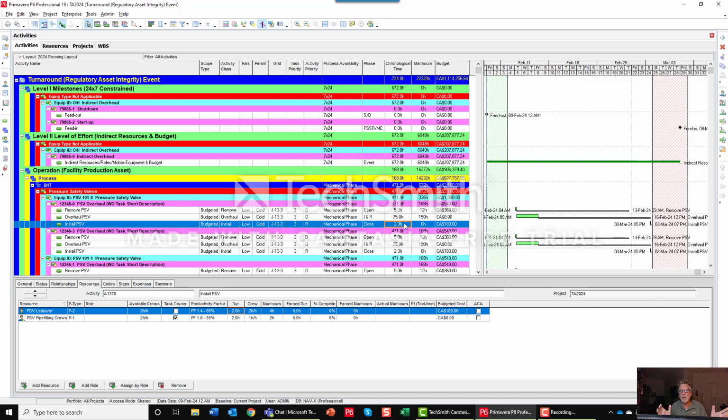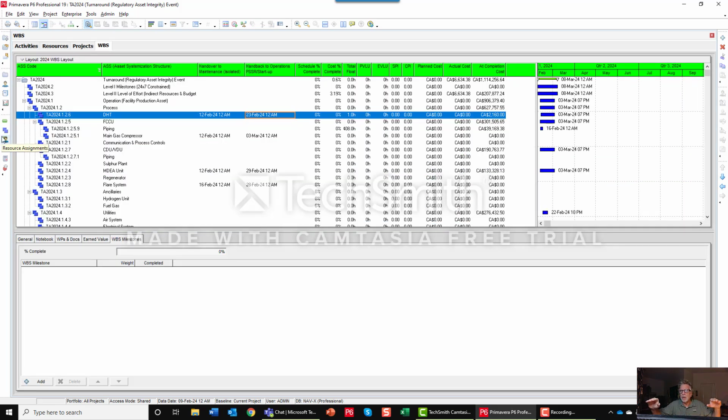So for now, remember, process availability, phasing your project: open, clean, inspect, repair, closure. Phasing is horizontal. It has a timeline. P6 does not phase, so you have to force it into phasing through calendars. The WBS should not be used. It should be turned into what we call the asset systemization structure, which is a vertical representation of the hierarchy of the physical asset.